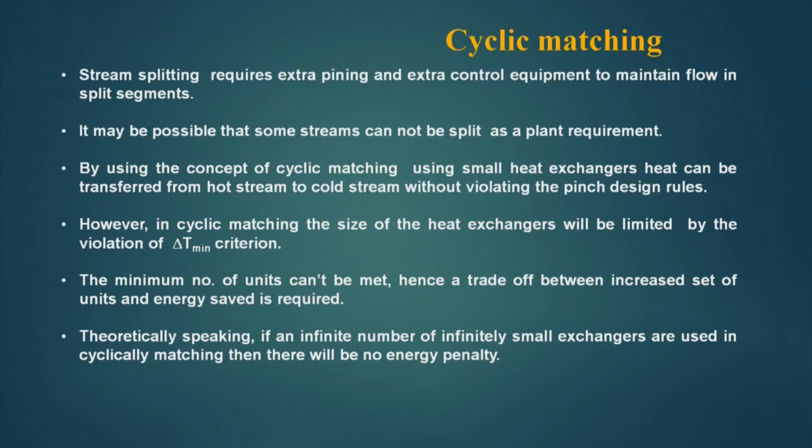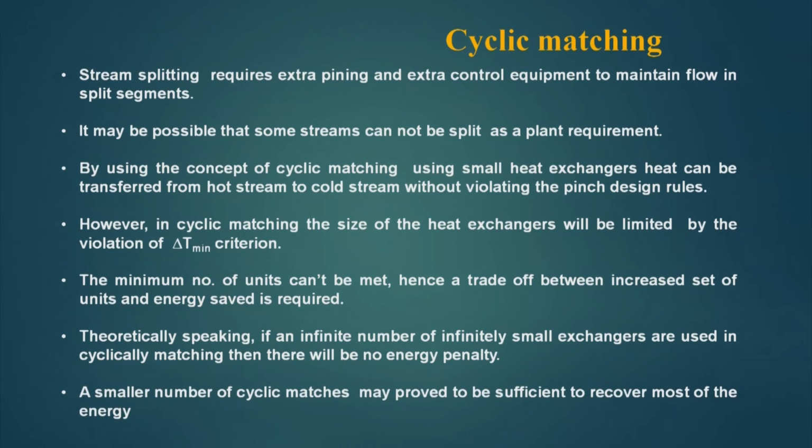Theoretically speaking, if an infinite number of infinitely small exchangers are used in cyclic matching, then there will be no energy penalty. This we will see in a numerical. A smaller number of cyclic matches may prove to be sufficient to recover most of the energy.